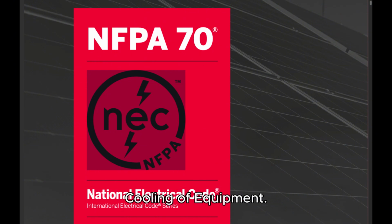110.13 Mounting and cooling of equipment. A. Mounting. Electrical equipment shall be firmly secured to the surface on which it is mounted. Wooden plugs driven into holes in masonry, concrete, plaster, or similar materials shall not be used. Informational Note Number 4: Minimum fastening provisions are provided in NFPA 5000-2015 Building Construction and Safety Code, the International Building Code (IBC), and the International Residential Code for One- and Two-Family Dwellings (IRC). B. Cooling.